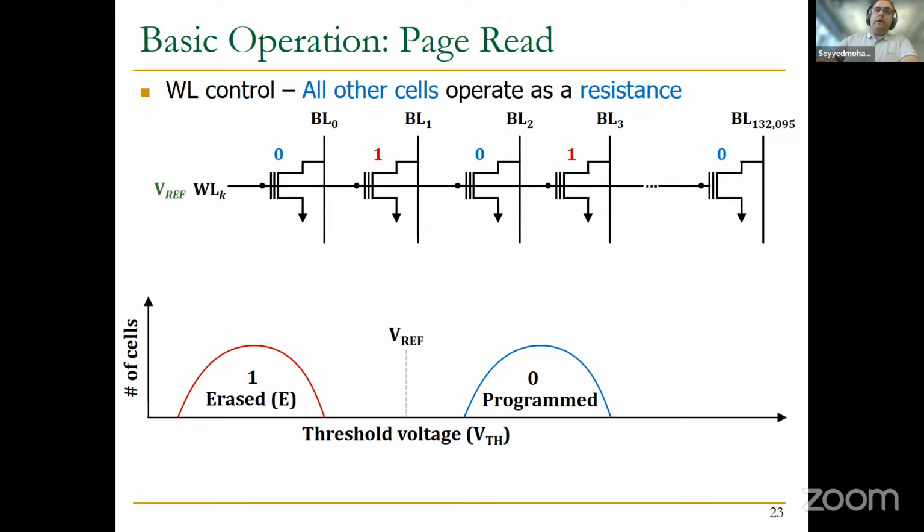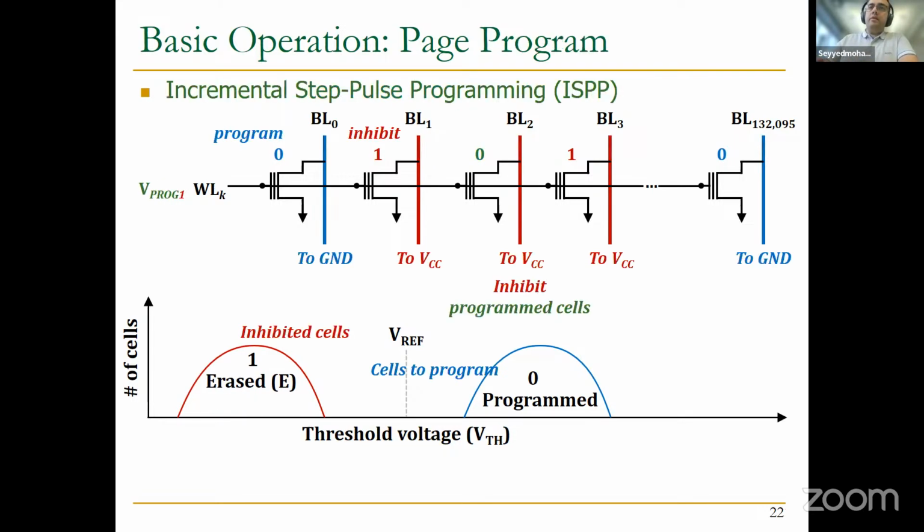So now let's see how we can read. By the way, here we only discuss SLC program. The technique for MLC or TLC is also similar to that. The only thing is that you need to have more resolution, and this incremental step pulse programming is going to be a bit harder because you will have different distributions in that page.